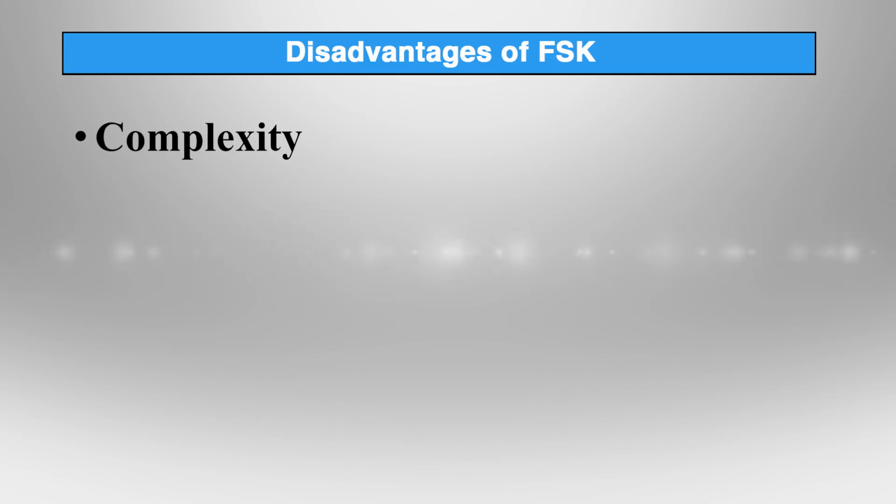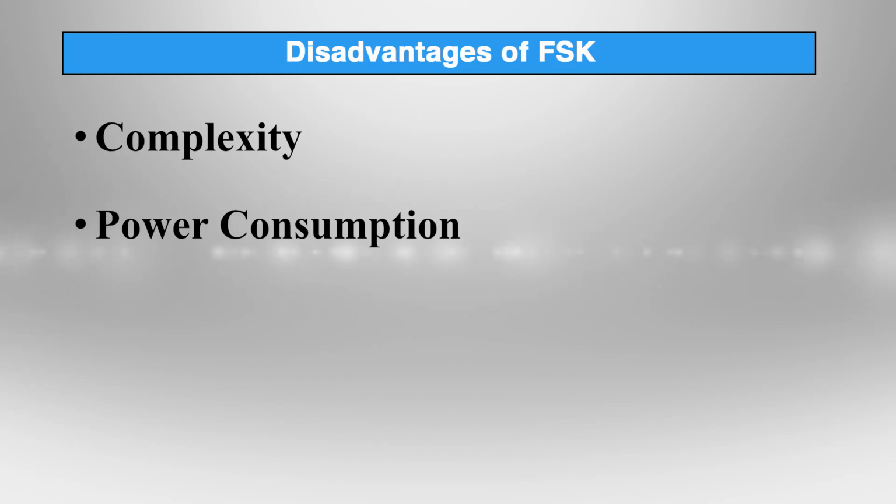Disadvantages of FSK: Complexity. FSK modulation and demodulation involve more complex circuitry compared to ASK, which can increase system complexity and cost. Power consumption: FSK can be less power efficient due to continuous transmission of the carrier signal, leading to higher power consumption.